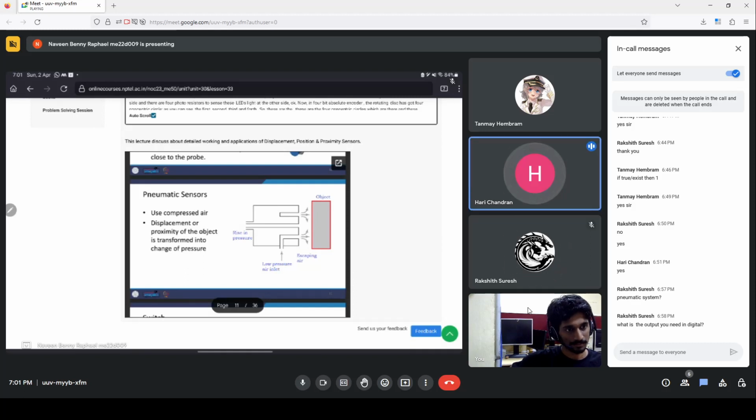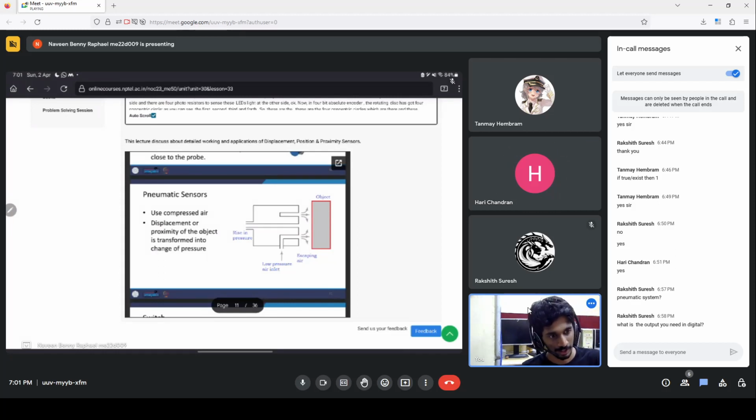Something like a resistance sensor can measure it. I guess one of the best ways to do it is to use the capsule pressure sensor. Essentially, the higher the pressure, the more the capsule expands, and the expansion of the capsule can be measured using a strain gauge. That strain gauge is essentially a resistance sensor, so we have a resistance output given a pressure change.